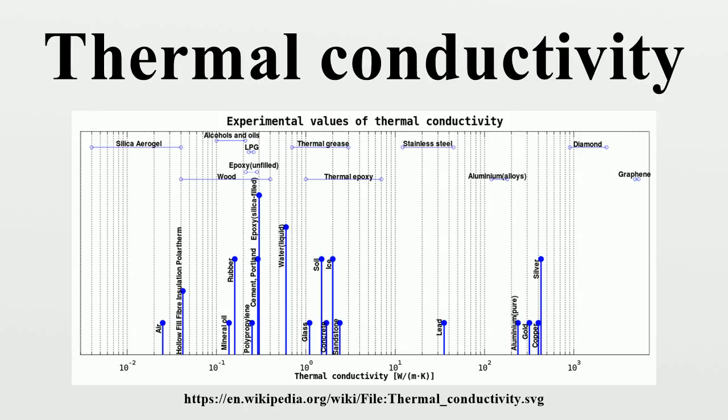Rs is the thermal resistance of the heat source, in °C/W. For example, if a component produces 100 W of heat, and has a thermal resistance of 0.5 °C/W, what is the maximum thermal resistance of the heat sink? Suppose the maximum temperature is 125 degrees Celsius, and the ambient temperature is 25 degrees Celsius, then delta T is 100 degrees Celsius. The heat sink's thermal resistance to ambient must then be 0.5 °C/W or less.